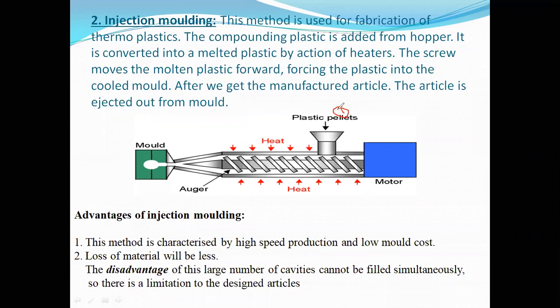When we take thermoplastics into the first chamber, known as the heating chamber, it is heated to high temperature, and I apply pressure with the help of the screw conveyor motor. This is a simultaneous application, which is nothing but temperature followed by pressure. When we apply temperature followed by pressure, we get liquid plastic,